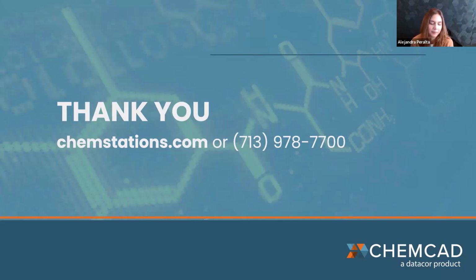The minimum that you need to create a component in ChemCAD is just the name and the normal boiling point. ChemCAD will try to give you some of the criticals for that and the eccentric factor, but that doesn't mean those are accurate. So it depends on what you need to model in the program. Depending on the equipment that you're going to be using, you will require certain types of data.